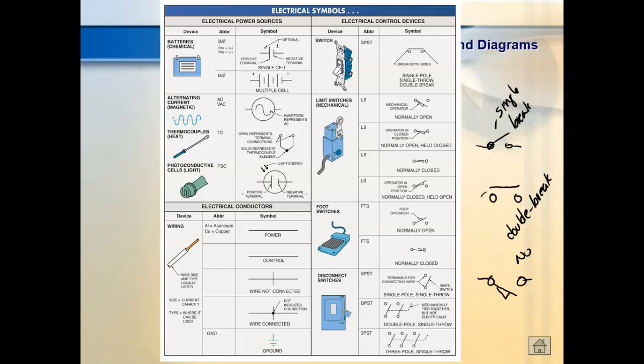Right now, when you get that limit switch, it's in a position, right? If you look at one set of contacts, they're closed, which means they make electrical contact and allow electrical current to flow through, and then another set is open. When you change position, the normally closed opens, and the normally open did what? Closed. Does that make sense? Okay. So this would be the symbol of a normally open contact. And then this right here would be the normally closed.